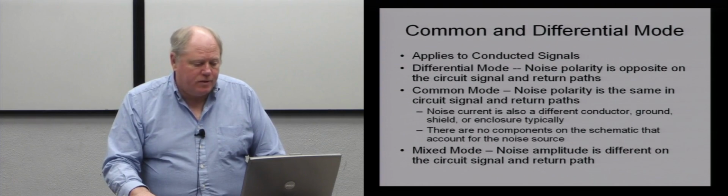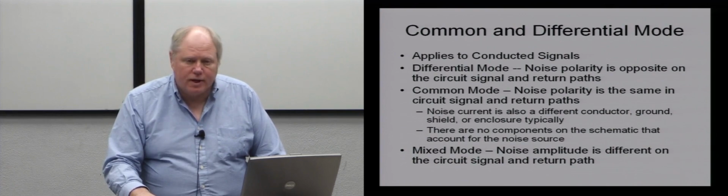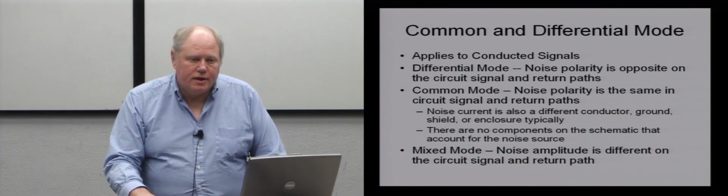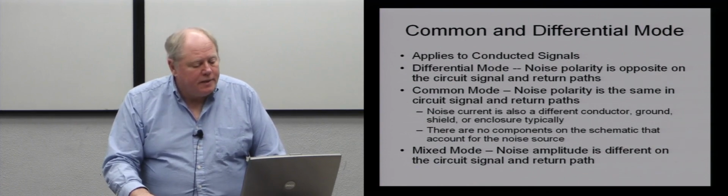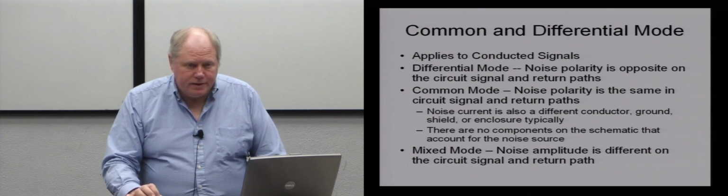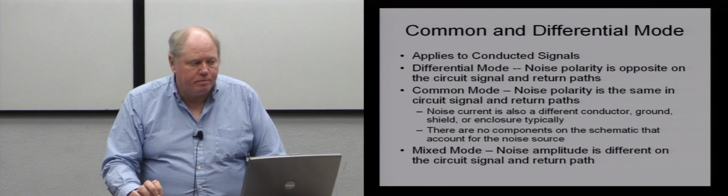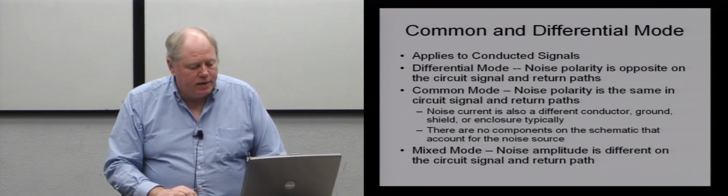Every piece of equipment that's going to tie to the utility is going to have some sort of ground connection that's meant typically not to carry any current. It's a safety ground. And that's why we have the three-prong plugs where the center is ground, or you have the two-prong plugs where one blade is wider than the other, and that's how you make the ground connection.